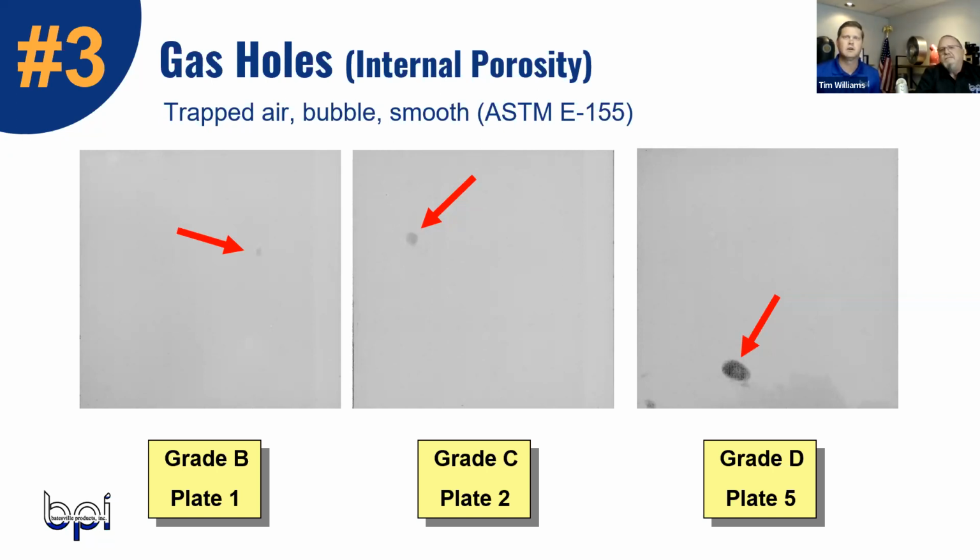Okay. So for anybody that's on today or anybody that has that type of question, is there a science to helping get that gas out? Is that slowing down the tilt pour? Is that on the molten metal side? A lot of it has to do with the runners and the gating. Okay. Slowing the velocity down or speeding it up, depending on what you want.